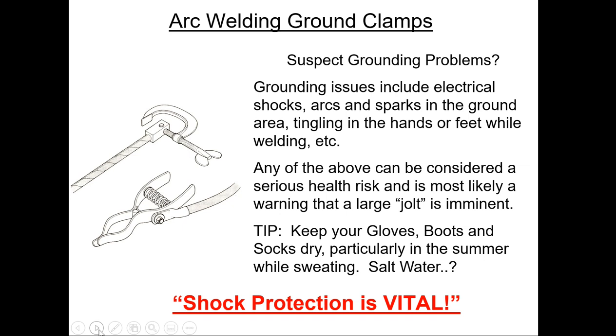We always have to make sure we got our ground clamps in a good position, and with this process, I always tell people that I prefer this type of ground clamp, the ground clamps that have a spring on them. And I do that because if a person ends up with an electric shock, and if you're going to get a shock, you're going to get a shock off this process. The high frequency in it likes to jump between one point and another, and absolutely loves it when you get sweaty. And I've seen many people get a pretty bad shock. If you have this type of ground clamp on, I can grab it and I can pull it off for safety. And I always keep that ground clamp within a step away from you.